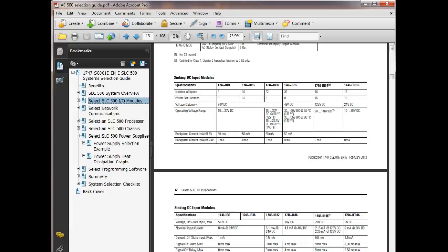Allen Bradley uses what they call the data highways, the 485 and then the data highway plus. And then the new PLCs have Ethernet on them, which is becoming very, very popular. The Siemens uses one called Profibus, which is very similar to the 485 interface. It uses the 9 pin. Odds are when you get out there in a big application, they're going to be connected together. And it still looks about the same. What you can do now is you can just plug into the bus on any other PLCs and access all of them. They have adapters that take the data highway and convert it over to Ethernet. So you literally could have an Ethernet connection in your office and access all the nodes out there in your plant.